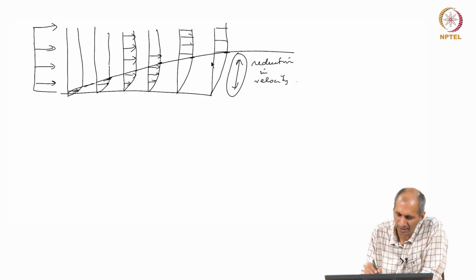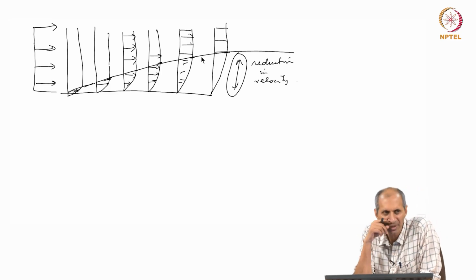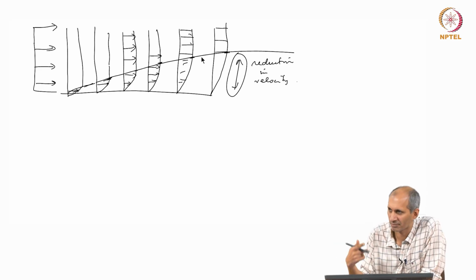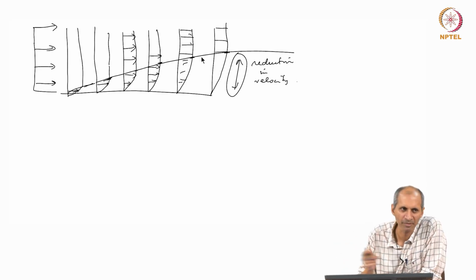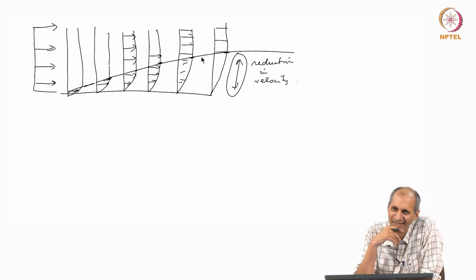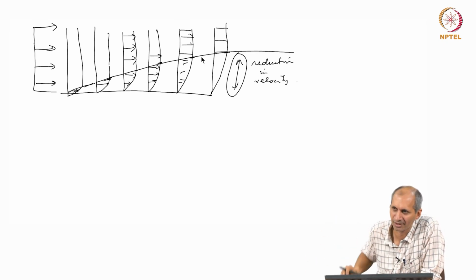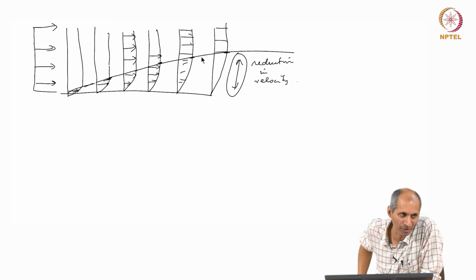It means that there is a velocity gradient. We have already mentioned that if the velocity is lower, then it is very unlikely to have very large convection. So, this is where the contradiction comes. Okay. The physical definition of boundary layer is this. There is a velocity gradient within the boundary layer. This is the fluid mechanical definition of boundary layer.